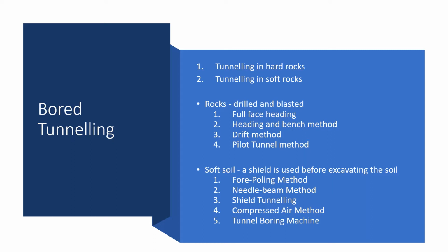Depending on the size of the tunnel, if the tunnel is wide, it requires more ground support as compared to a narrow tunnel. Then again it depends upon the type of ground, as I told you, the nature of soil or strata met with, whether it is a hard rock or a soft soil. So different boring methods are followed depending upon the type of ground, the equipment available, the sequence of excavation, and the size of the tunnel.